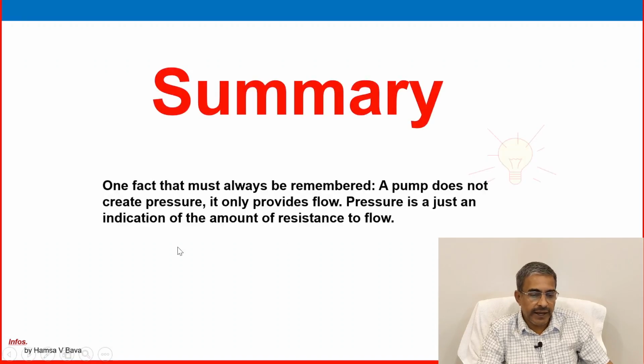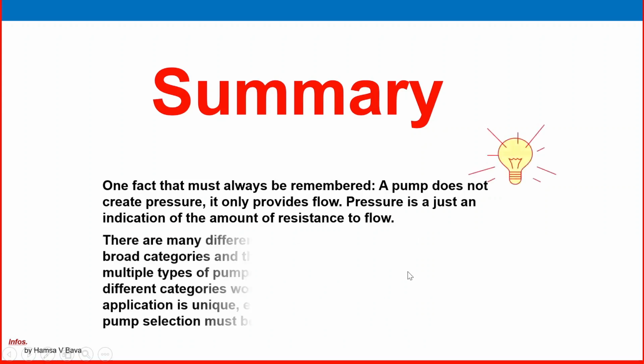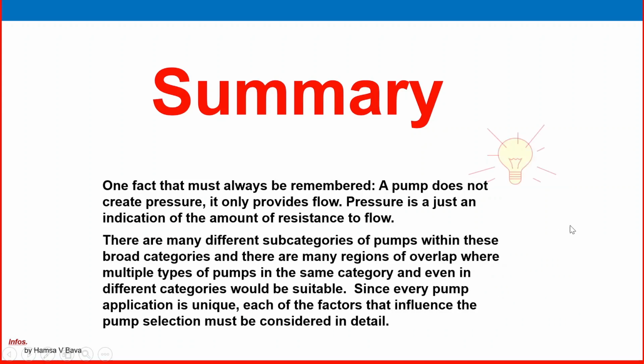So the summary is coming, and one fact that must always be remembered: a pump does not create pressure, it only provides flow. Pressure is just an indication of the amount of resistance to the flow. There are many different subcategories of pumps within these broad categories, and there are many regions of overlap where multiple types of pumps in the same category, and even in different categories, would be suitable. Since every pump application is unique, each of the factors that influence the pump selection must be considered in detail.